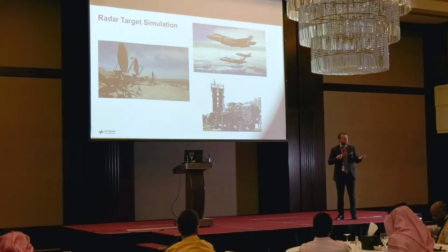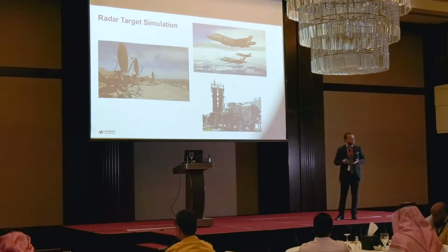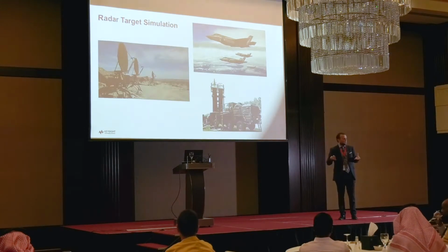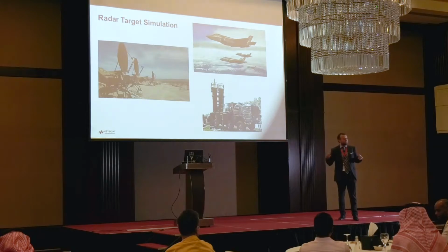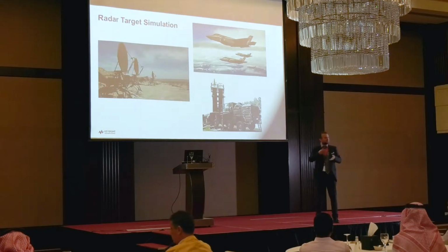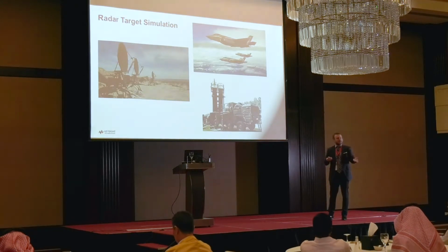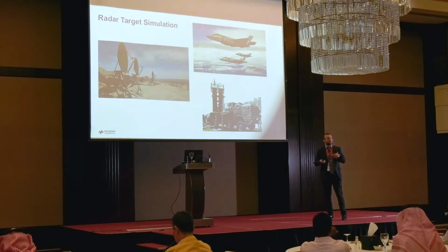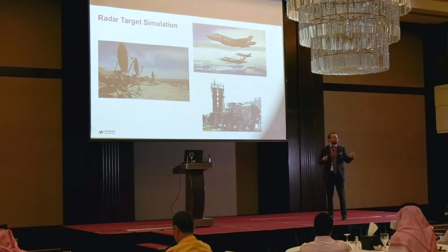And we can build scenarios for a signal source and build up complex waveforms and pulse parameters, and build into that signal a lot of the detail that we can have in an environment. But an EW system is complex, and we need to be able to see how it reacts to other countermeasures. So for a given system, we may want to provide some complexity to it during the test. And that's where the radar target simulator comes in. And this is basically, as the title suggests, simulating the return signal of a radar system.